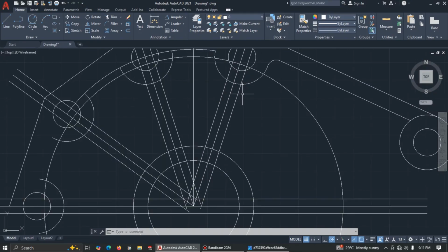So for us to add a fillet, I would like to use this one. So tan radius, then 5. It's okay. Press enter to repeat again. So let me just click here, press enter. Now click here again, click here, enter. Click tan radius, click here, enter.